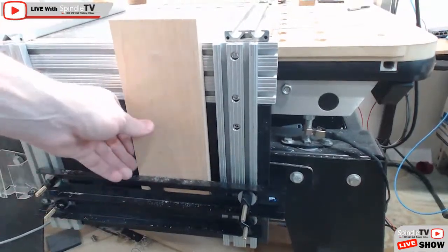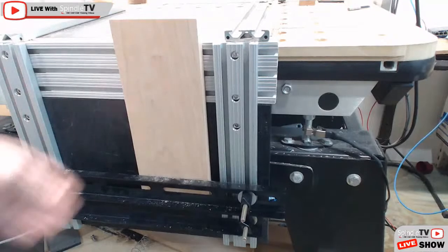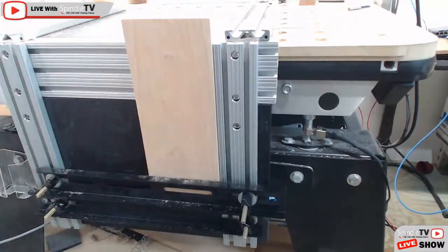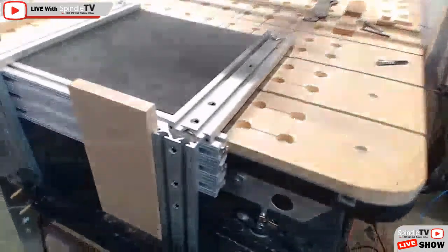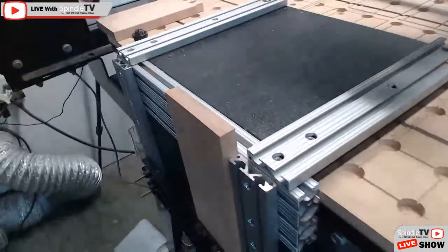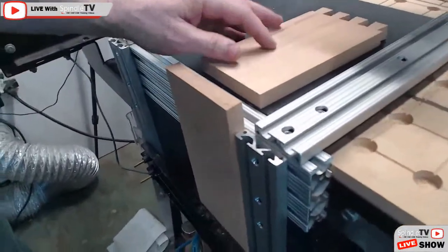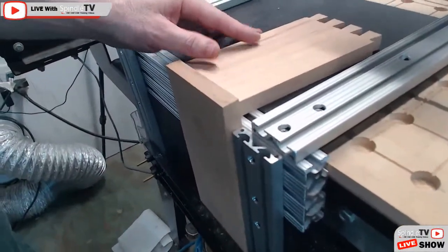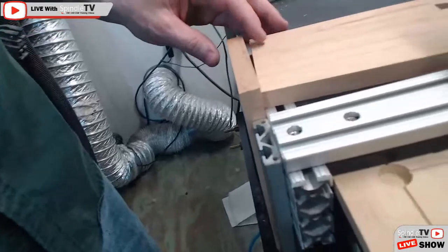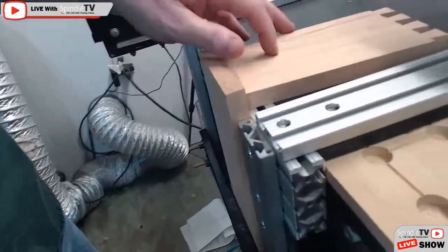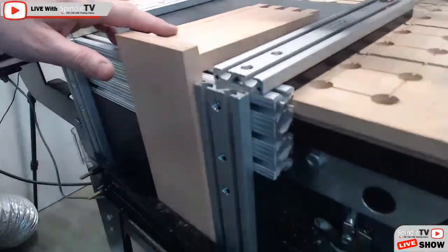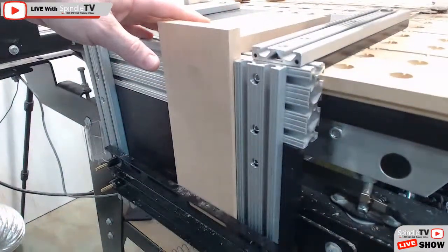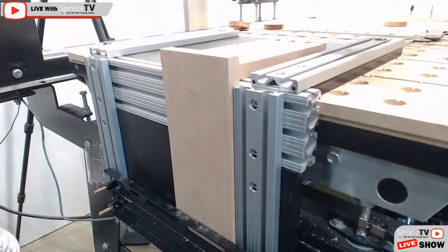Set at 10 inches so I could just set the board right down on it and slide it over where I need it. Now, that particular setting, let's come over here from the top. That particular setting is at least the thickness of my horizontal board plus some extra, because if you remember, I like to cut my parts proud. I want them somewhat proud when I'm assembling them, and then I will sand them flush.